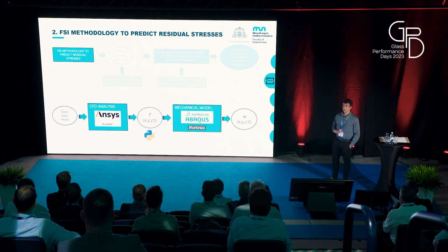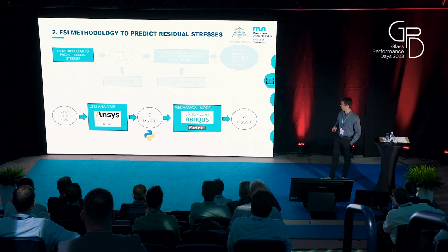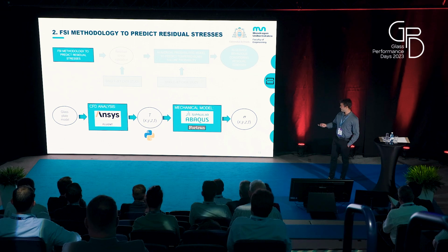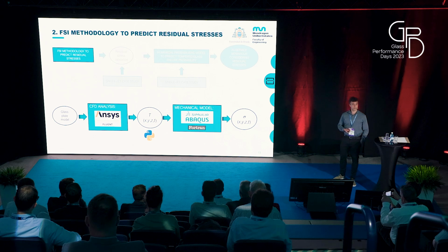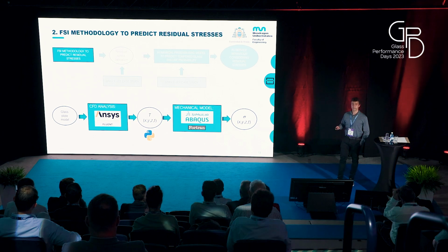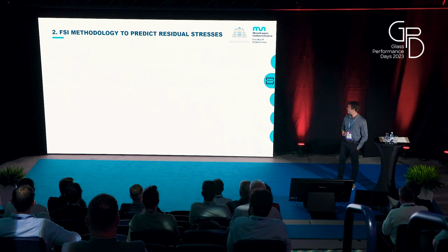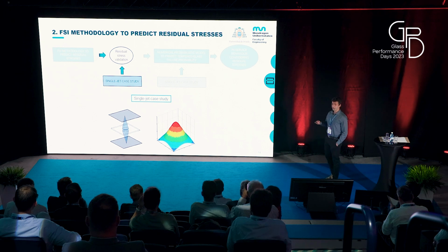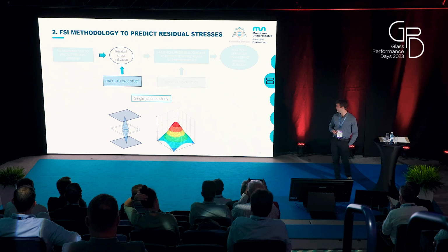In this context, what we propose is a computational fluid dynamic analysis to obtain the non-uniform and transient temperature distribution in glass, and we transfer it to a mechanical model where we consider the viscoelasticity and structural relaxation phenomena of glass. In this way, we are able to predict the non-uniform and transient residual stresses. For validation purposes, we propose a single jet case study that was carried out in the facilities of the University of Mondragon.